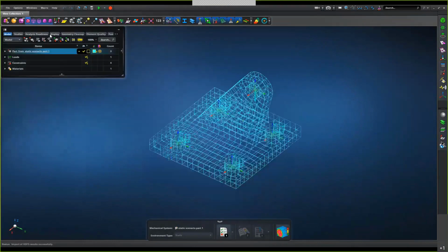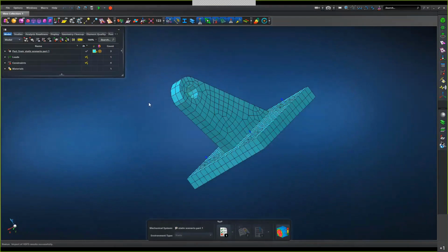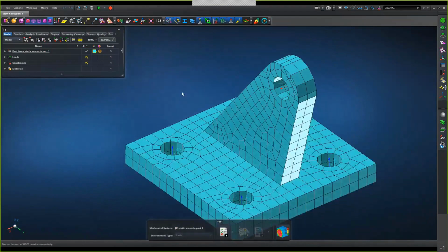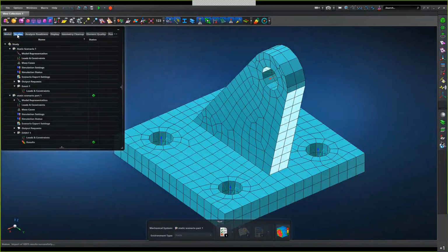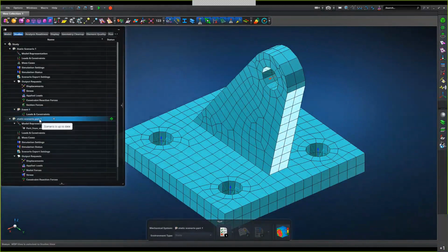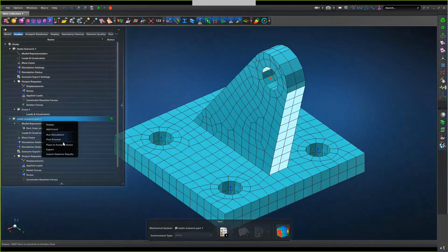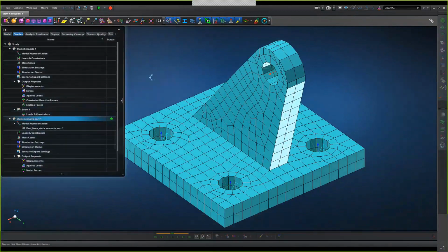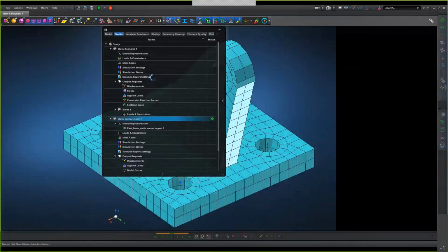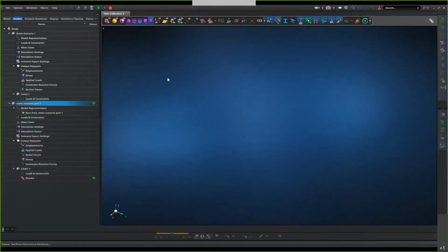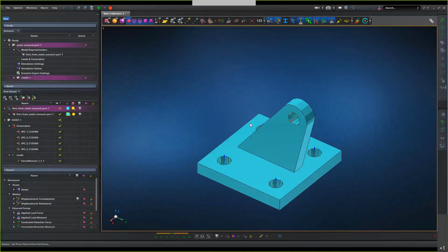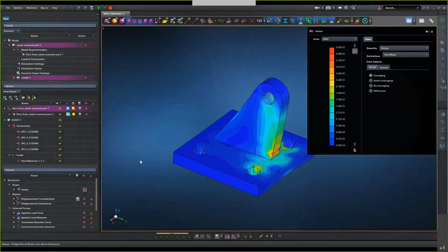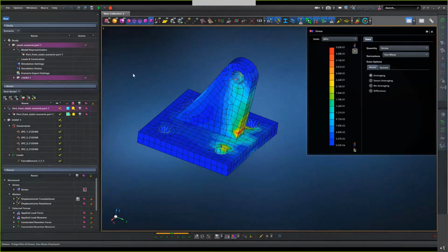And let me close that, and then I can go directly into post-processing as soon as I verify, yep, that's my model. And then I go to the Studies tab, and lo and behold, now I no longer have to right-click and say import results. It's already imported. Now I just have to, just like normal, right-click and say post-process as if it ran internally using the built-in solver. Okay, and there are my results. So we're good to go there. Okay.